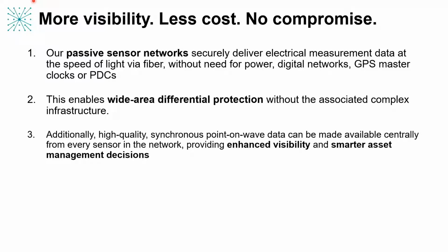Now, quite a unique aspect of this technology is that you have that high quality, synchronized point-on-wave data available at a central location. So this means that beyond serving that data to traditional protection relays and informing conventional protection architectures, what we have is an instrumentation system that will centrally deliver granular data from a very wide area. So beyond simple protection applications, it can also be expanded and used to improve visibility and to inform smarter asset management decisions.